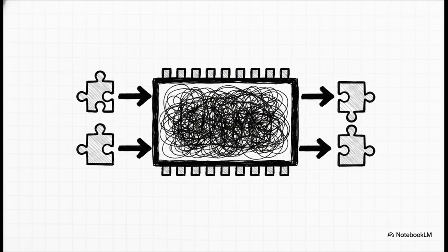Data always flows left to right, inputs to outputs. The complicated math happening inside the block is totally hidden from you, kind of like a physical computer chip. That makes them perfect for dropping into critical tasks like PID control loops, all while strictly enforcing those data type connections we talked about earlier so nothing crashes.